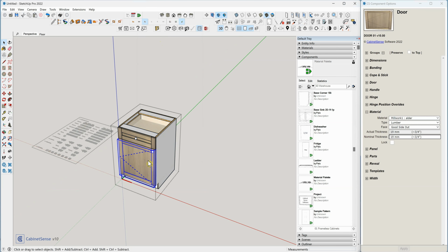So you can set the thicknesses on the carcass, the door, the drawer box. So if you wanted, for example, go back to the carcass, if you wanted a back of 1/2 of an inch, it's now 1/2 of an inch. But let's say this one stretcher that we put in, we do want it to be 1/2 inch. What we want to do is lock it. This is going to prevent the project component from forcing a change onto that specific part.